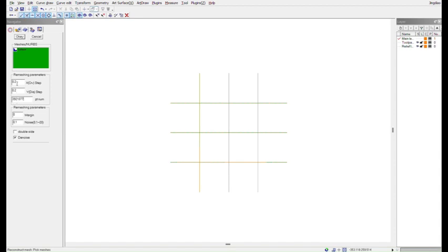So you have to make sure you understand the steps one by one. The tool is going to wear according to these factor parameters. So carefully you have to select this number of meshes, because the time consumed for the block is limited here, and if you reduce it, that time is going to reduce, but the tool will wear more.